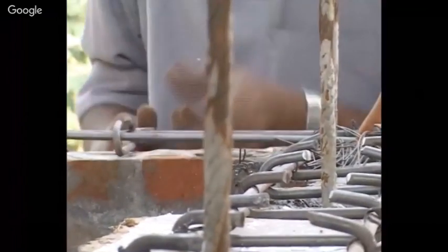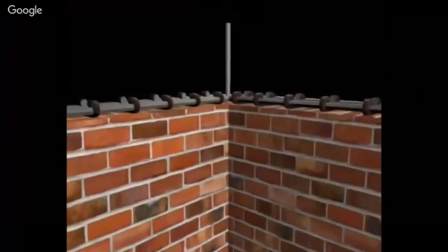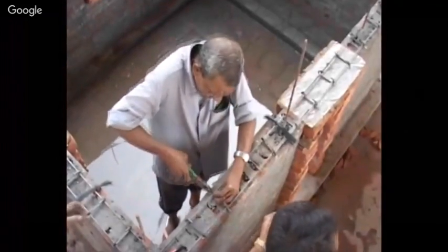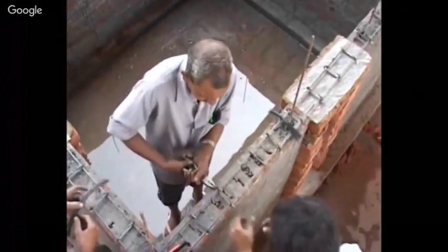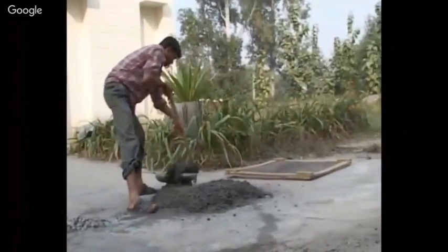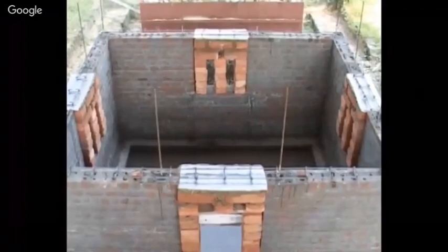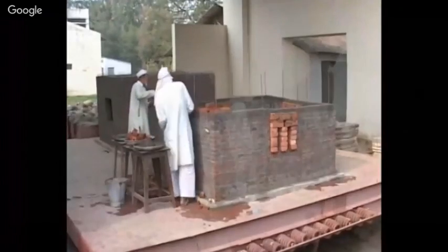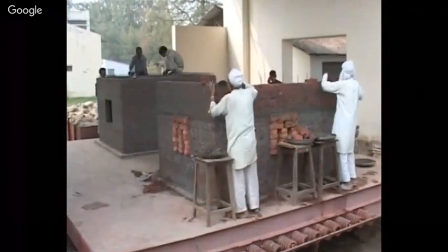In the actual construction, vertical reinforcement is embedded in the plinth masonry into the foundation and is passed through the lintel band and anchored into the roof slab to develop its tensile strength. The reinforced concrete band has the same width as the thickness of wall. The vertical thickness is kept to the half scale. Then the wall is completed up to the roof level and the roof slab is laid as was done for the traditional model.